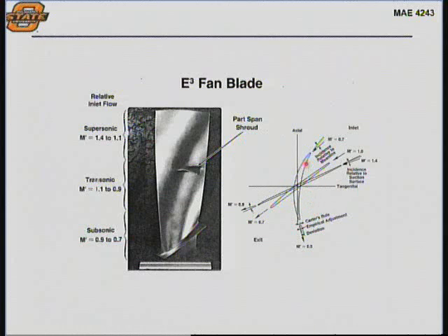So over on the right, see if you can see how this is pictured. Think of flow coming from top to bottom. Near the hub, you've got this type of airfoil shape, which has a fairly large thickness. Again, there are structural reasons why you might want to do this. But the angle of attack relative to the flow is going to be much different because of the relative velocity being dependent upon the wheel speed U, which is omega times R. R is really low here, so U is lower than at the tip, which means the angle is going to be different.